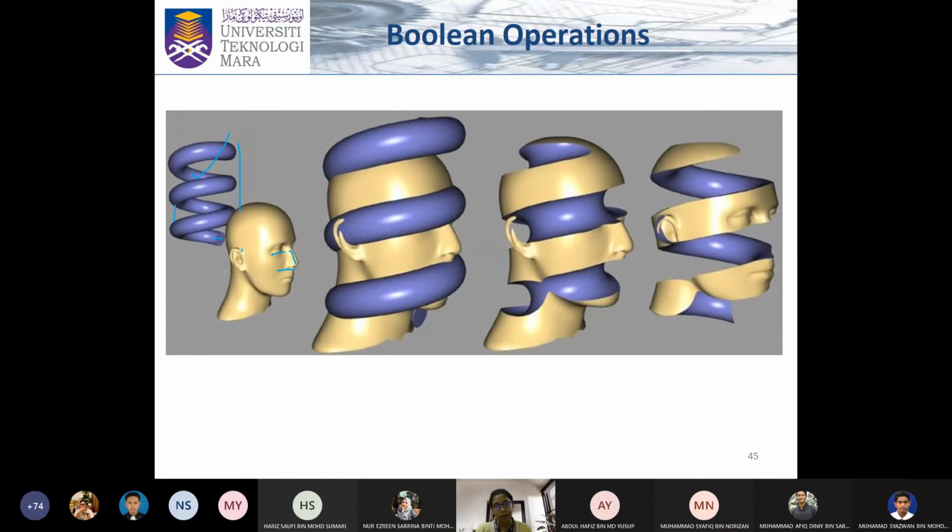So organic shapes like this, what do we usually do? We scan them, or we actually reverse engineer them by scanning the entire data in. How do we scan them? We use multiple digital points, right? We actually either have a touch probe on each of these areas, all right? As many data points as possible will ensure that your model is closer to accuracy. Or we can just actually do rough scanning, right, and import the surface image and then create a solid outcome.